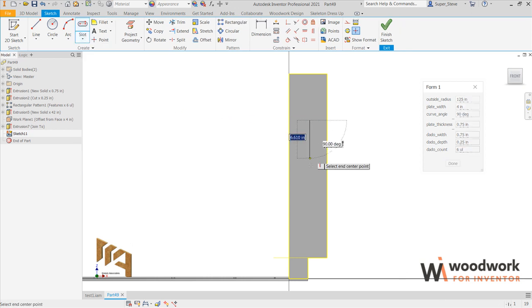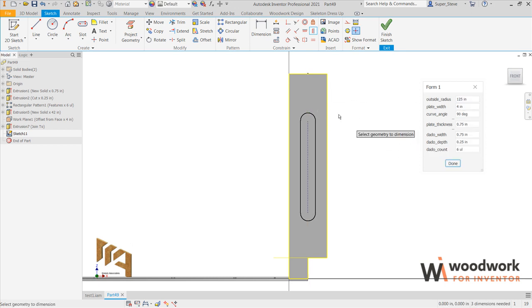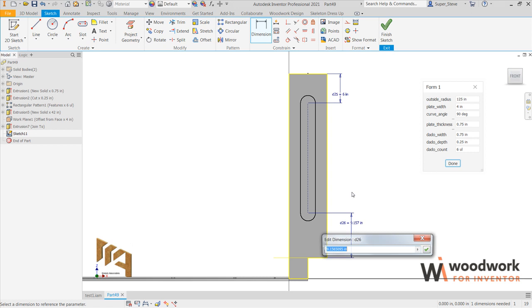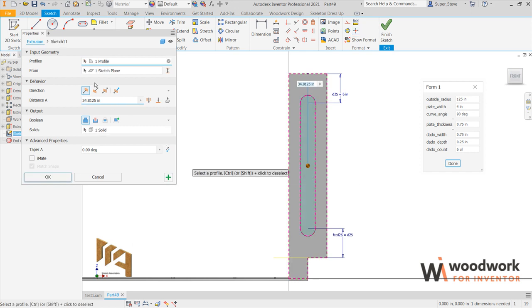And let's say it does have a cutout in it. Many ribs have some form of a cutout in it. I'll make an oval cutout. I'll also center it in the cutout and also set it up so that it's a certain distance off the top. Let's say 6 inches off the top and 6 inches off the bottom where the kick ends. That means no matter how high the kick is, the slot is always going to be 6 off the top and bottom.